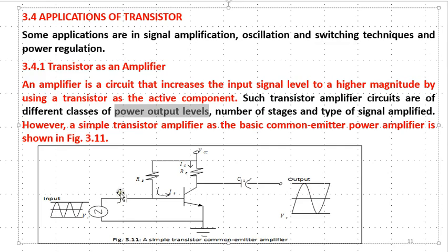And we have a capacitor here, we call it the blocking capacitor. Its function is to make sure that all the DC components in the signal are blocked, only the AC are allowed to pass. And these two resistors, RB and RC, they are biasing resistors. Their function is to supply the required voltages and current to the base and the collector. And this capacitor, we call it a coupling capacitor. It is the capacitor we use for matching the impedance of the output of this transistor at the collector and the input impedance of the device we are going to drive, like an amplifier or so.